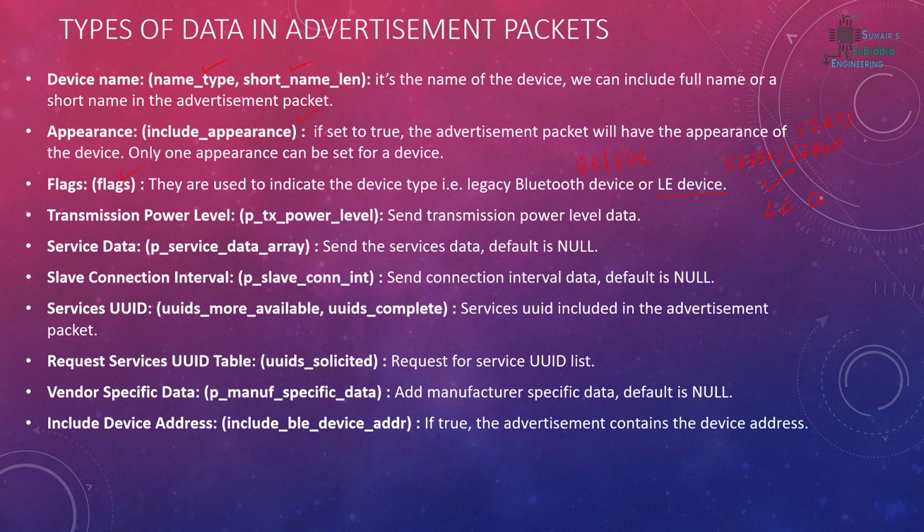They support only the LE or low energy type. These devices are LE, so we can include that in our flags so the connecting device knows what type of device it is. In the flags we can also include whether our device is advertising for an unlimited period of time or just for a limited period of time. We will see what flags we need to include for that, to show our connecting devices what type of device ours is.